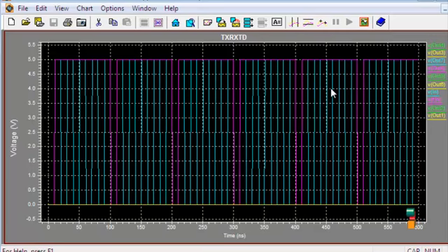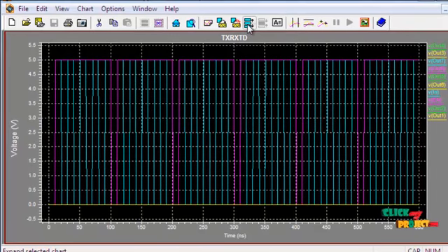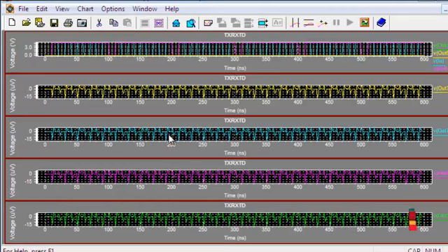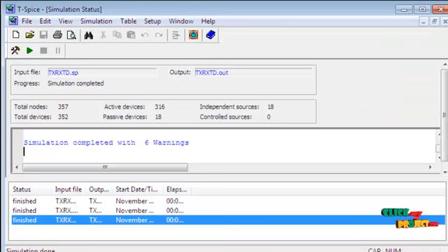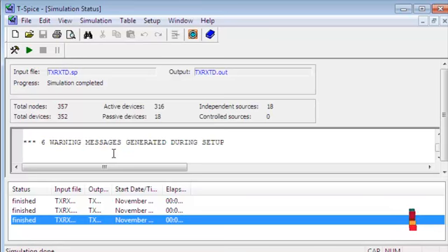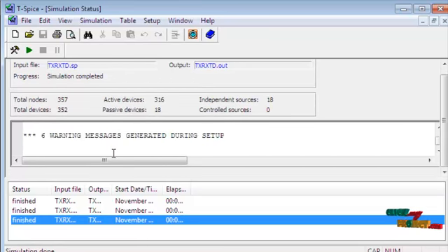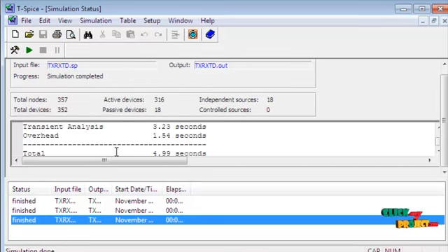If you want to view them separately, click the expanded chart, and the data will be shown in a separate view. This is the output waveform, and we are also able to calculate the power and time. This is the time waveform, and this time value is obtained in the tSpice window.